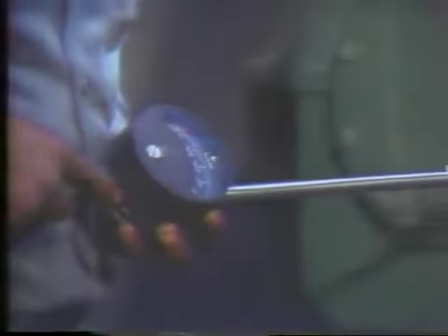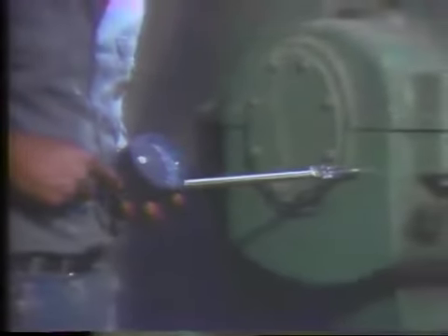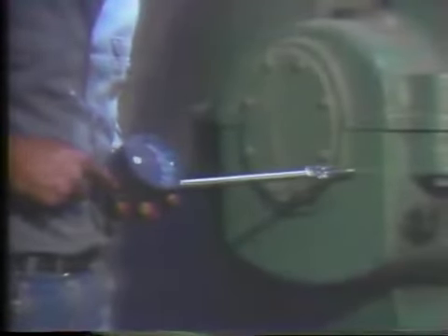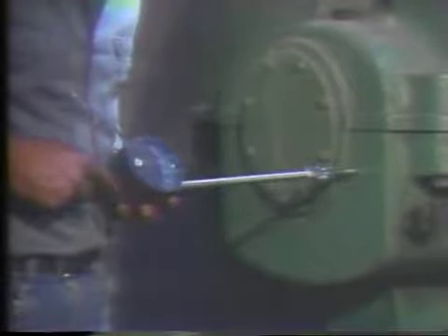There are also instruments for determining temperature. This operator is using a pyrometer to measure the temperature of a bearing housing. The probe is placed on the bearing housing and held there for a period of time to allow the probe to warm up. Then, the temperature can be read directly from the pyrometer. One thing to remember when taking temperature readings is that they will not be accurate until the equipment is operated a certain amount of time. This time is different for each piece of equipment and is called startup time. You must be certain to allow a bearing enough time to reach its operating temperature before you take your readings.